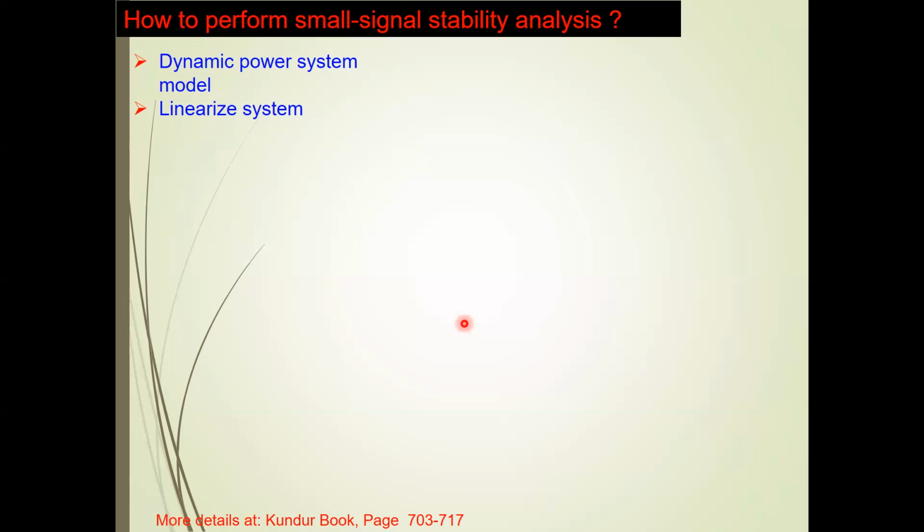The load is not linear at all. Which type of load? I mean, if you have a motor, for example, or some kind of load that is unknown. Yes, a motor is non-linear because it involves dynamics in the rotor. In fact, the speed of the motor will change. And if you have a rectifier also, electronic loads, or an electric arc furnace, those are all non-linear loads. But if you consider lighting load, those are static loads actually.